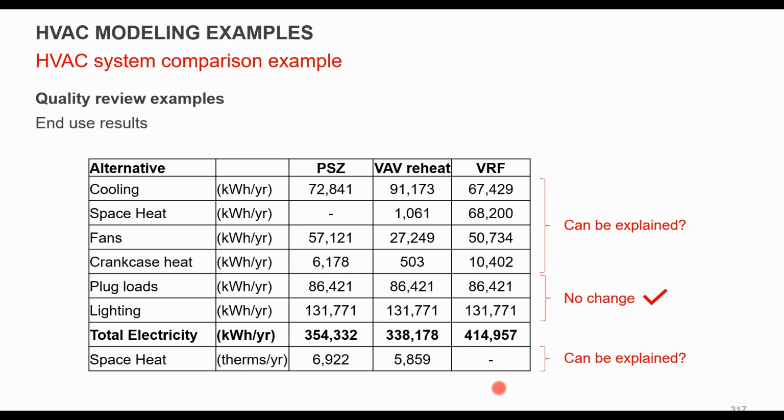There's a firm out of Vancouver that's done this as well. I don't think ASHRAE has a specific guidance in the handbook, or actually I think it's HVAC Applications. There is a methodology of dealing with heat loss and heat gain in a pool, because you've got to account for solar that's actually adding to your pool and whether you have covers and all these other things. So there are ways to do it. We have a custom tool that we've built. I don't think it's great, but it helps at least a little bit with that.